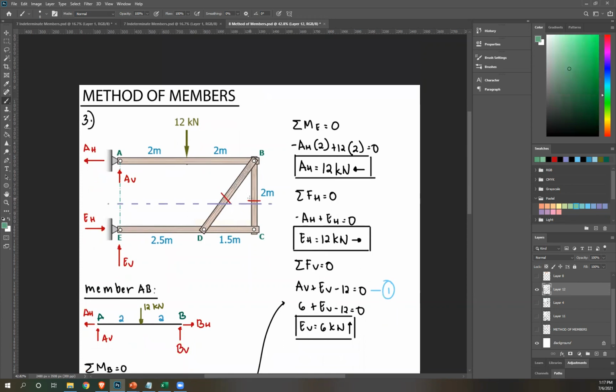Okay, so this is 1.5, this is 2. Right? Again, this is the slope of the member that we need. So 1.5 and 2. Now, if you try multiplying those two values by 2, right? 2 times 2, 4. 1.5 times 2, that's 3. So this becomes 3, 4. And we all know the hypotenuse of a 3, 4 right triangle. That's 5. So you can do that just to make things easier. So it's a 3, 4, 5 right triangle for slope.